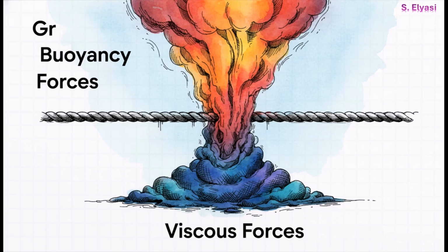Up top, in the numerator, you've got all the forces that are driving the flow. There's g, gravity. Without it, the engine doesn't start. Then there's beta, our expansion coefficient, multiplied by the temperature difference between the wall and the fluid. That whole chunk together is the source of our buoyancy. A bigger temperature difference gives you a stronger upward push. Then we have x cubed, which is a length term. Buoyancy acts on the whole volume of the fluid, so that gives it scale.